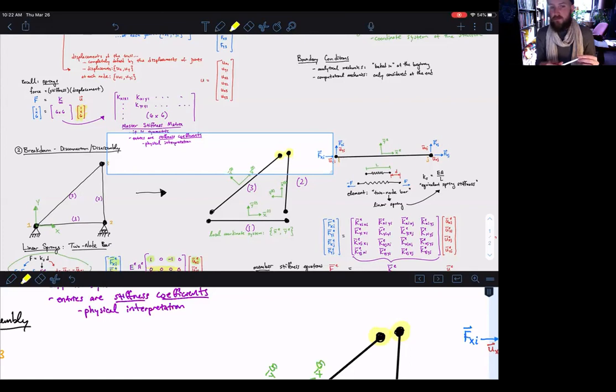Yes, from what I understood, in my local coordinate system the displacement might be 0, but then when I move to the global one, it might not. So I have to not put it to 0. Exactly, because you might have this member trying to push it this way in response to that force, whereas this one, actually a better way would be this one in response to an X force is going to have some Y component, or X component, I had it right the first time.